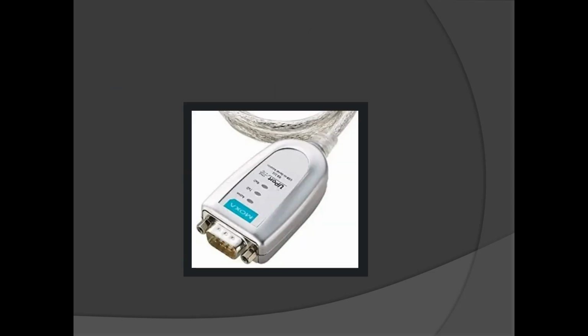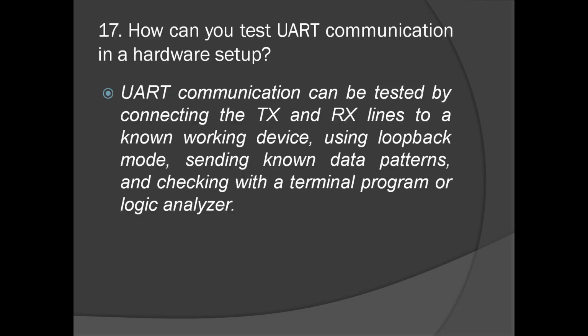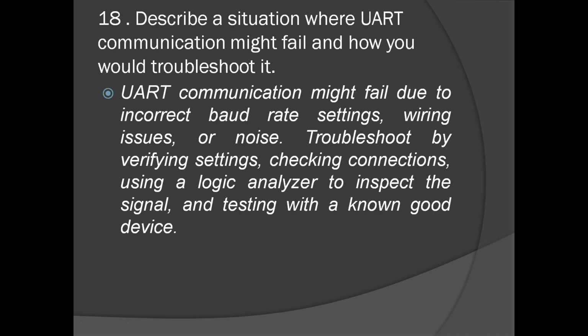Yeah, sir. Like when we connect with some working device, that same data we will send through the transmission wire of UART, and the same data we will receive from the receiver line. So we will check whether the same data we are receiving or not. By this way, we can check how the UART module is working or not. Okay, for everyone. We can connect only a maximum of two devices, so there is no intervention that can happen from outside. Simple data frame. It is only a simple data frame.